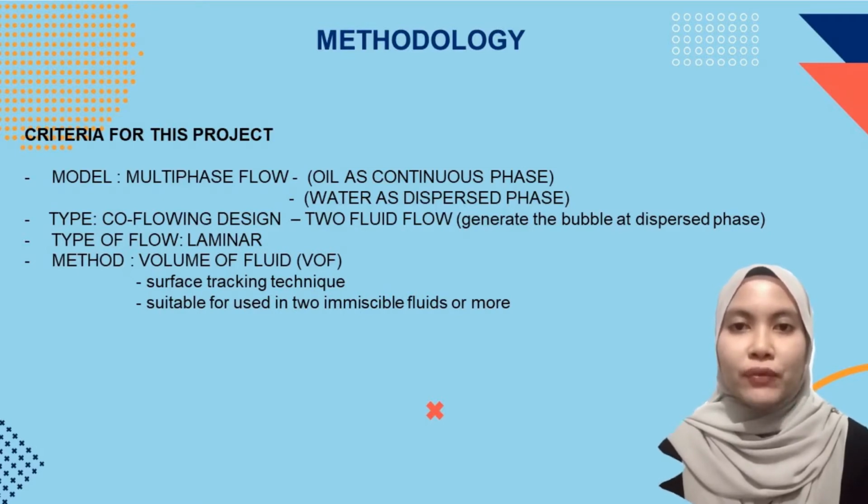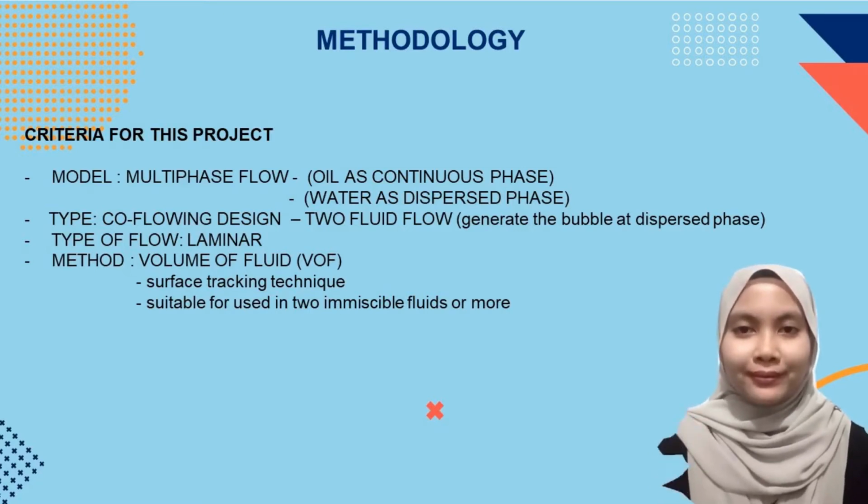The flow that is used is laminar flow as we want to get a smooth flow of bubble formation. And the method that is used is VOF, which is volume of fluid. This method is used because it has a surface tracking technique that can be used in fluid flow, and it is also a suitable method to analyze two or more immiscible fluids.